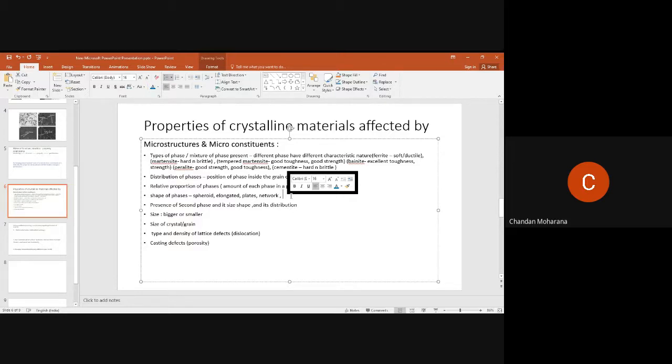Spherical. Spherical one is good. How can you justify that? Already you have studied mechanical metallurgy, that is your deformation behavior. You have heard about the stress riser, stress concentration sites. I told you in IPM, I remember. The area increases in spheroid. So what will happen to stress? Stress concentration is more in the pointed one.